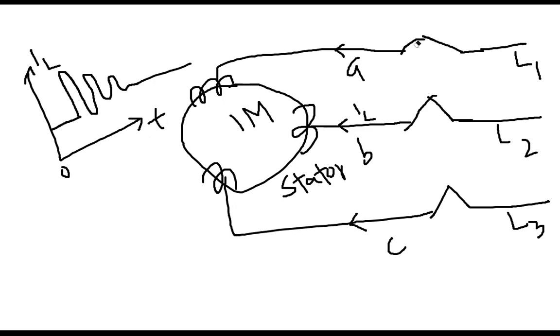Before closing, first attach some sort of a small reactor, I mean an inductance. Once you have the inductor, then you close. So these are the L, the small value of L.